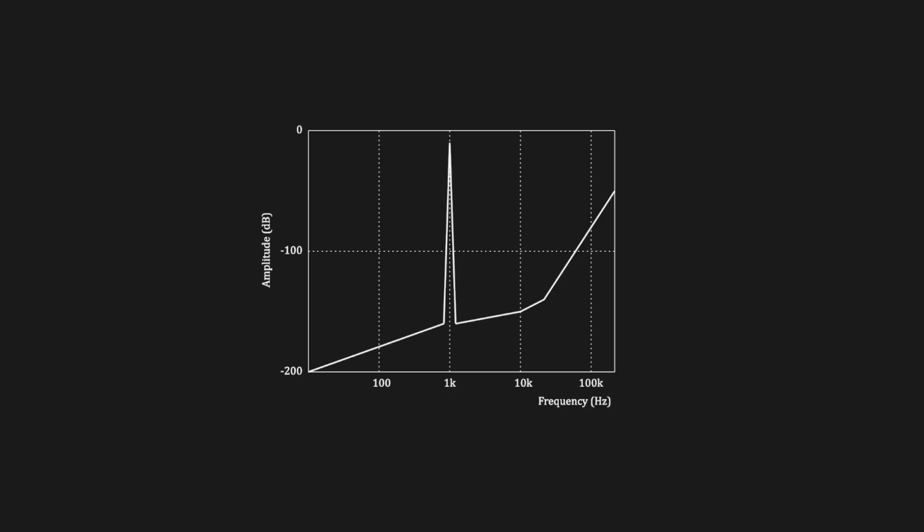DSD relies on sigma-delta modulation and noise shaping. The human ear can't easily hear very high-frequency noise, especially if it's not related to lower-frequency sounds. So, DSD pushes most of its noise above 20 kHz, where it's not noticeable. Advanced noise shaping filters, often fifth order, reduce audible noise even further. A simple low-pass filter can then remove the remaining high-frequency noise and recover the audio signal.